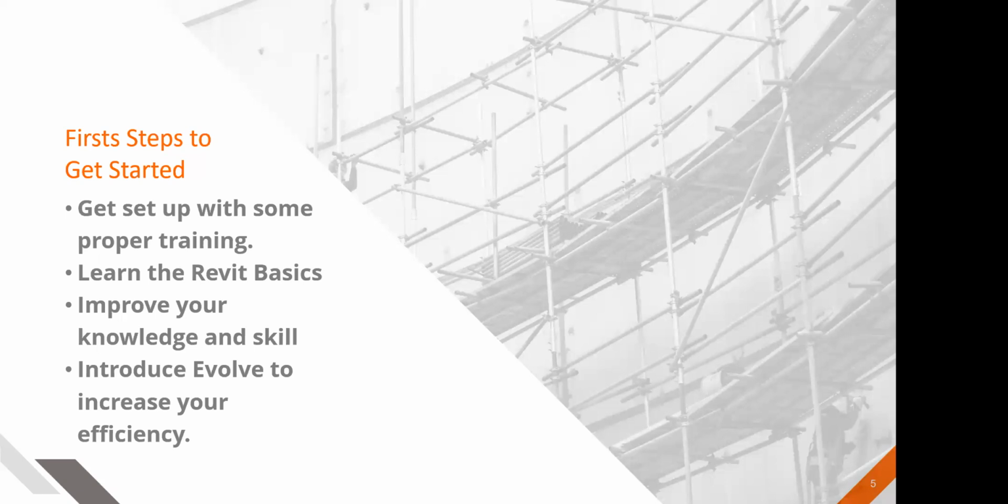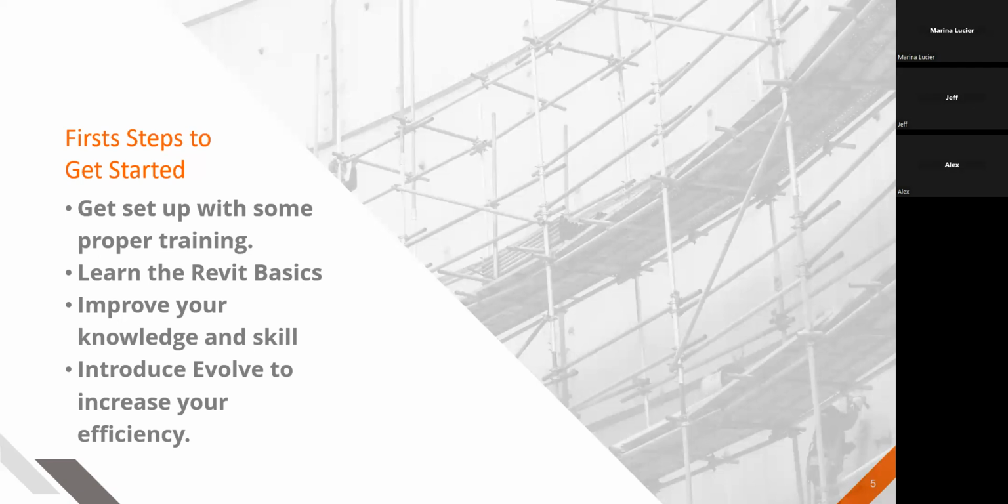Layers and blocks are different within Revit. You no longer turn on layers and blocks, you turn off items and categories. So if I didn't want to see the wall layer, I would just turn off walls as categories within Revit. Line styles can be determined based on what you're using. It's change, that's all it is. It's just trying to get there and get everyone on that same level.